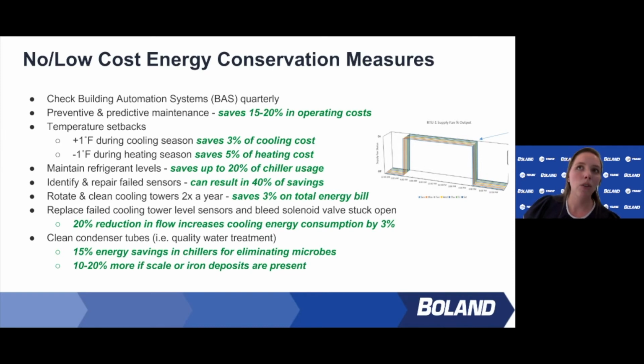There might have been an event and you had to run your equipment till 9 p.m. You might have forgotten that the schedule's running till 9. So for the month after, you had everything running till 9 when your building's empty at 5. Things like this will help you catch those and then help you save money going forward. We also recommend an easy thing you can do, or you can contact somebody to help you program this, is to investigate your temperatures for unoccupied hours and also during heating and cooling seasons.